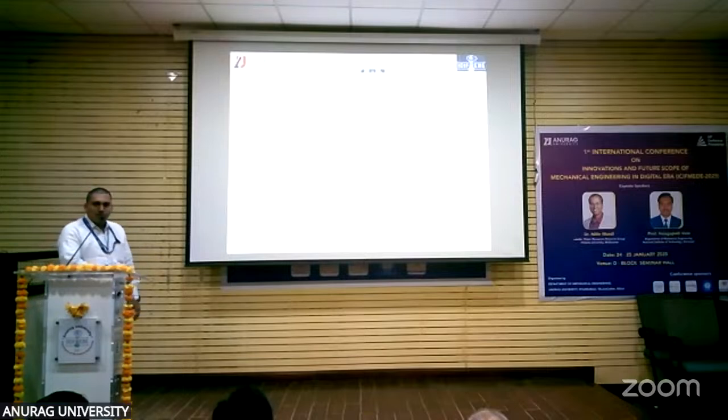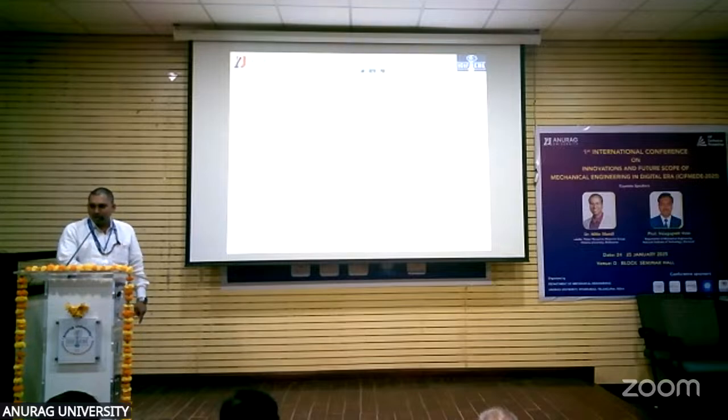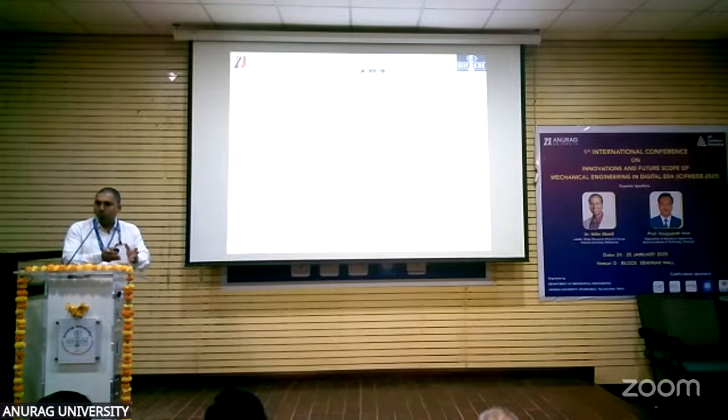And this is the total annual performance of the PV system from January to December. The major amount of power we received was in the month of March, and the minimum power we got was in the month of December because of climatic conditions. For yearly performance, the performance ratio we got is 75.46. The plant efficiency is 12% average, inverter efficiency is 97.46, and system efficiency is 11.68 for the total year. But this value varies based on the capacities and on how properly the systems are maintained.